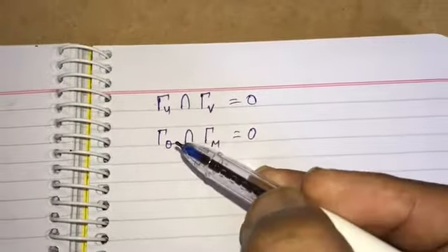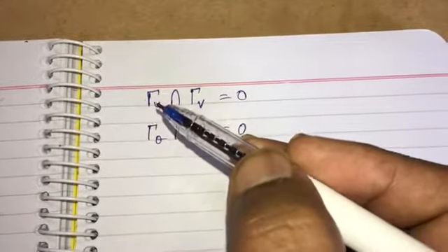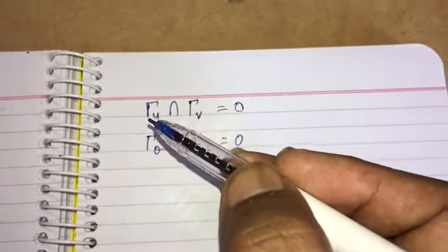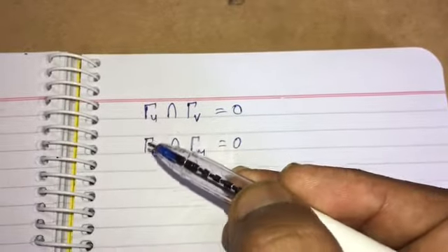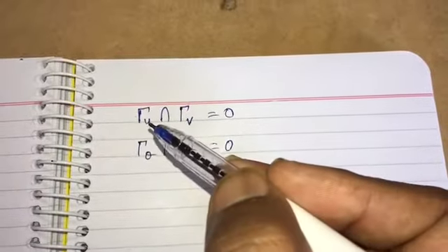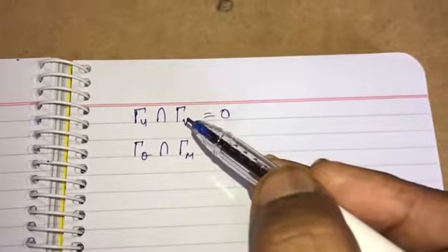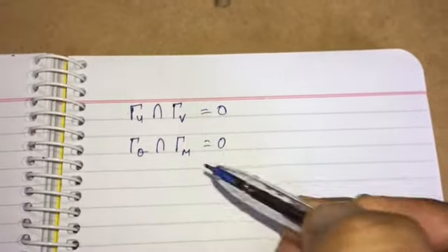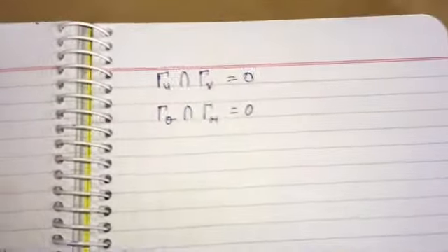You can give a displacement and a slope, that is possible, but you cannot give displacement and shear force. So remember those.